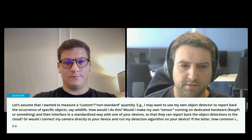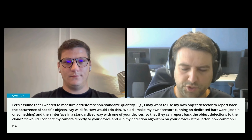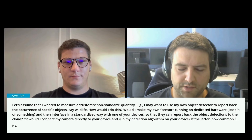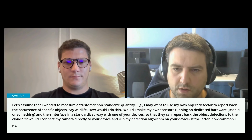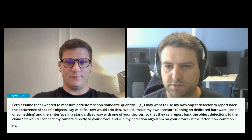And if you're trying to detect things where your machine learning model is so large that it won't fit in the dedicated flash for the application processor, or the RAM requirements are not sufficient, then you probably need to use a Linux-capable device like a single board computer.